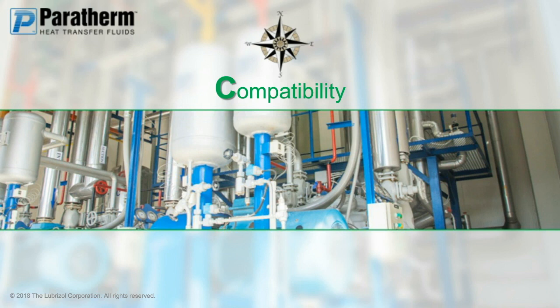Even more common, though, and more of a cause for concern for compatibility is the fluid-fluid compatibility. So existing fluid replacement, extremely important. Get it tested. Make sure that whatever the degradation level is in that system isn't going to be something that's going to immediately contaminate and hurt the new fluid that you're putting in. When you're looking at existing fluid replacement, top off versus drain and recharge is very important.